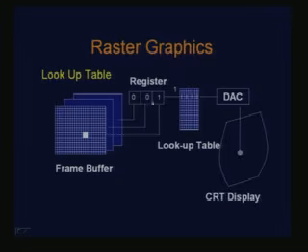Depending on the value of this register, which earlier was getting mapped to the intensity value, now I do something different. I define a lookup table for which the width is clearly larger than the number of bits I have for the register. That is where I will do the augmentation.